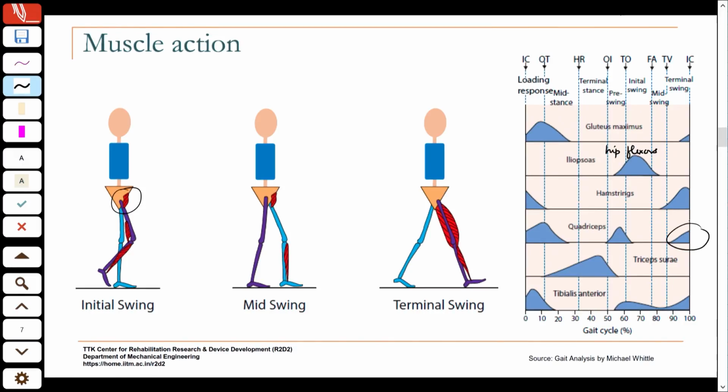Okay. The gravity cannot alone make it swing forward like that, and so you may need what is called an extension assist. You want something that will help, because you do not have the quadriceps muscle. If the amputation is above the knee joint, here you have the quadriceps acting to help extend the swinging leg, which would be absent in the case of a prosthetic leg, and so you may have to have an additional extension assist in order to help it do that.